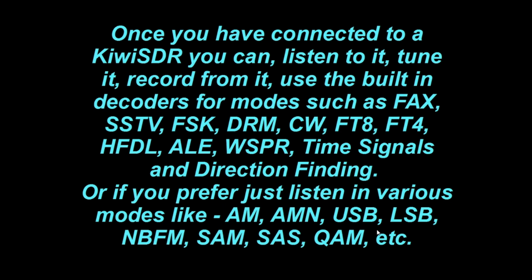So once you've connected to a KiwiSDR, you can listen to it, tune it, record from it, use the built-in decoders for modes such as fax, SSTV, FSK, DRM, CW, FT8, FT4, HFDL, ALE, Whisper. There's time signals you can decode, and even direction finding, where you use multiple KiwiSDRs in conjunction with one another to actually give you a time difference means of direction finding.